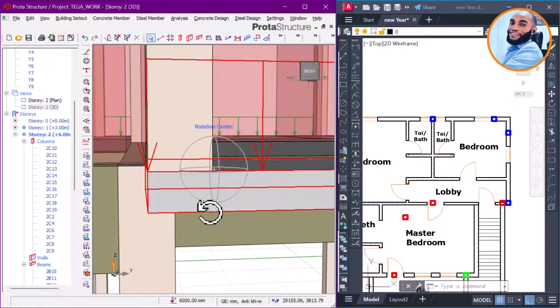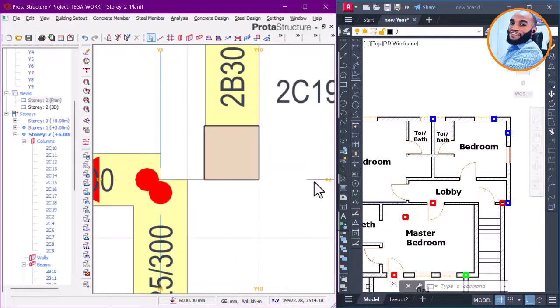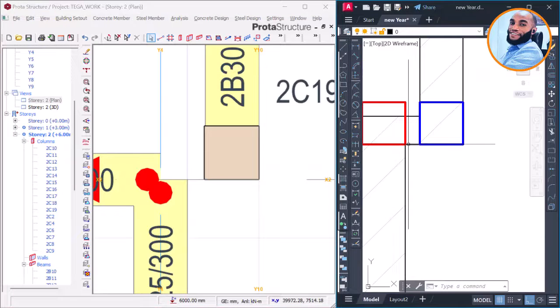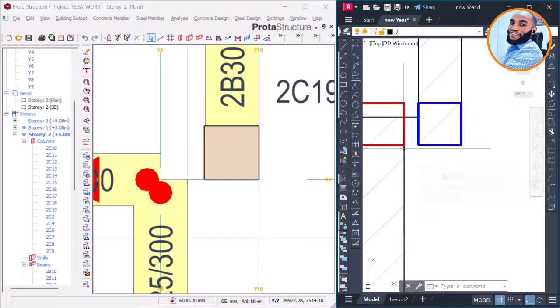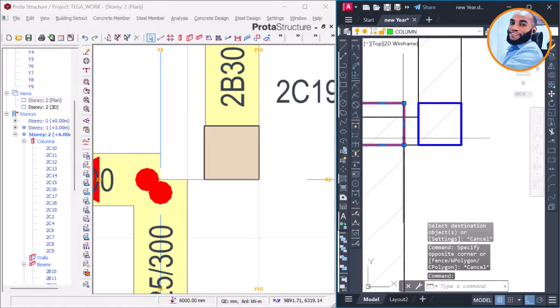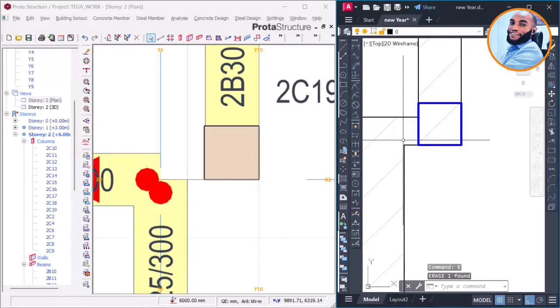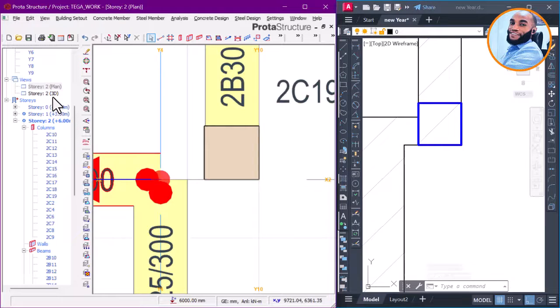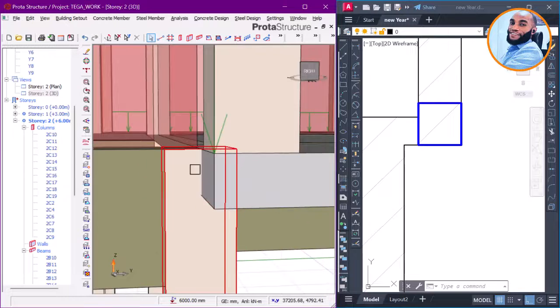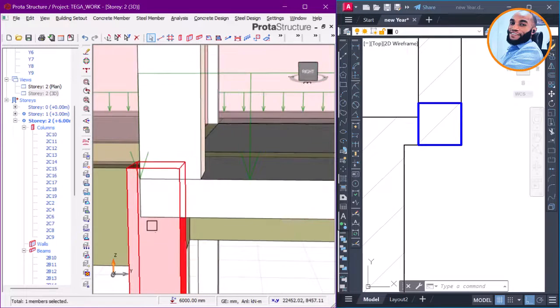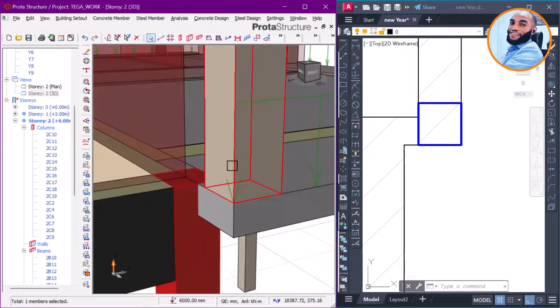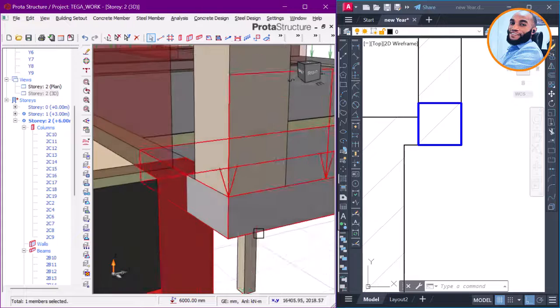Now that but is that if you look at this cantilever again, you can see that it is flushing with the edge here. Can you see the edge here? What it means is that this is the column below, which you have moved. If we go to 3D view here, you can see what is happening. This column is the column below, and it is meant to flush together. That means this cantilever slab is meant to flush here and not to end on the grid line.